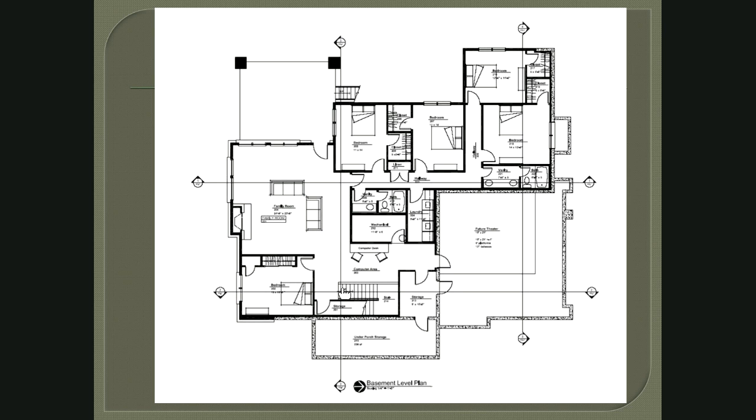This is stairs. So when you cut through the stairs, these stairs are going down, and these stairs here, this is a closet. The reason I know that they're going down is you'll see all of the stair as it's going down until you hit the floor of whatever this storage area is. When you're going up, you only see the stairs up to a 4-foot point, and then you'll see a break line in there. Let's see, what else can I point out on here?